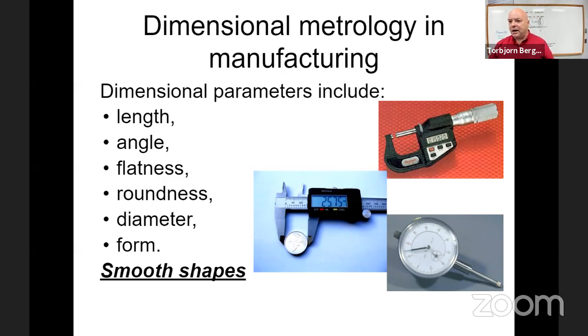Hardness. To measure hardness, what we do is we take something, we push on our material with a known force. It makes a plastic deformation in our material. We leave a dent in the material after we push on it. It helps if you take something that's really hard and really small when you're doing the pushing, and you look at the size of the dent that it left in the material, and from that you can infer what the hardness is. So yeah, we can measure hardness. We have to measure length and force in order to measure hardness.